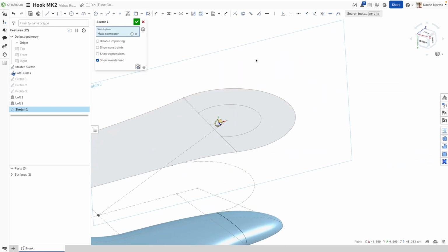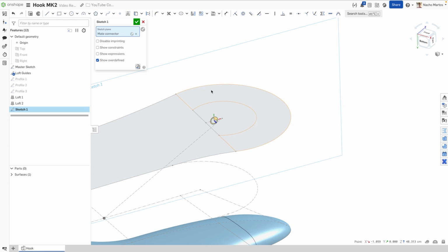So from here, we're actually going to define the exterior geometry of just that attachment as a surface. To do so, I will be using the ellipse tool. We can build an ellipse that is horizontal, and then I'm not going to worry too much about that. So we don't really care about that dimension. We're about to delete that, and then we will make the exterior dimension 6. So deleting this dimension, we now want to make these piercing and to also make these piercing. Now we fully defined that within the plane.